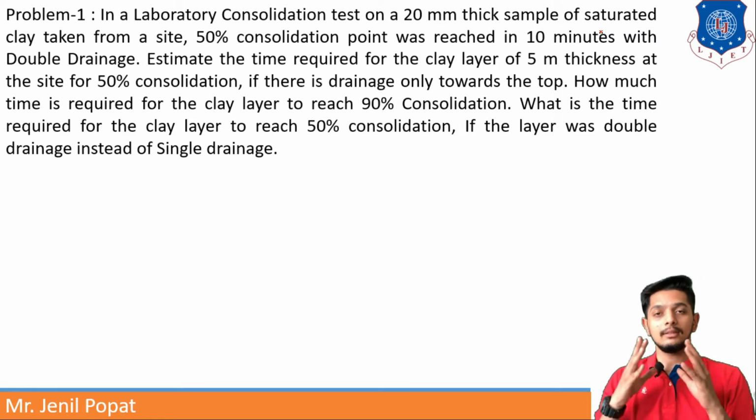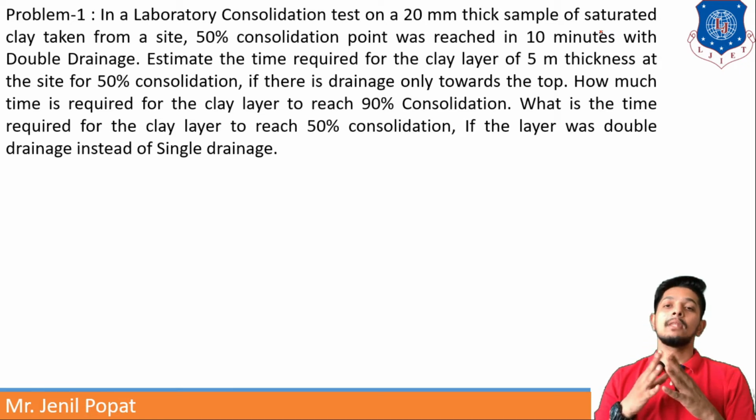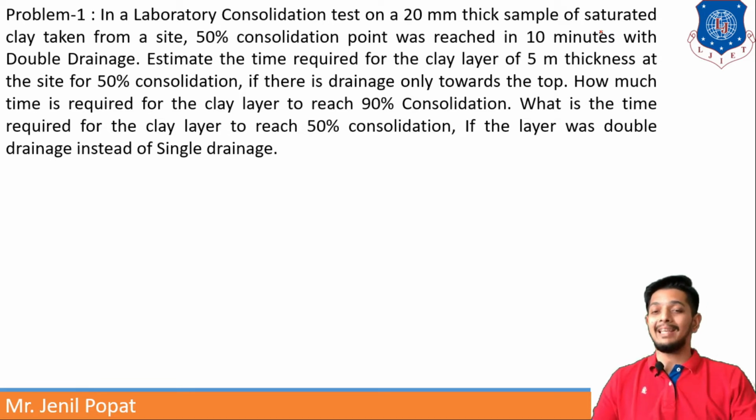Here a sample is taken from the site for laboratory testing, and the 20 mm thick sample reached 50% consolidation in 10 minutes with double drainage. So the height should be considered as half. Estimate the time required for a clay layer of 5 meter thickness at the site for 50% consolidation.